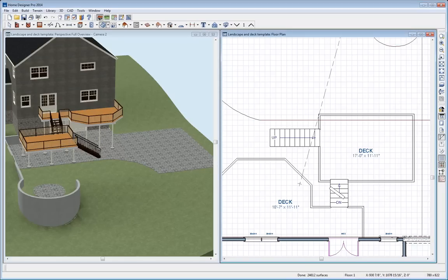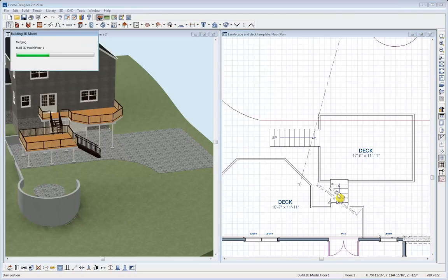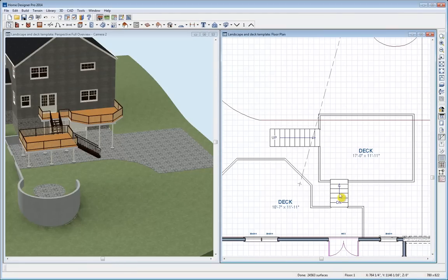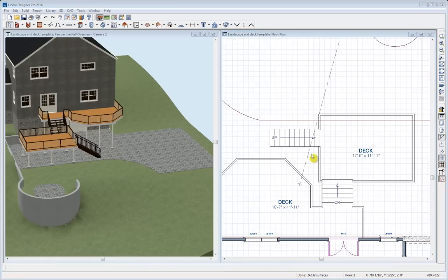And then I do also want to, I accidentally drew out a stair there. We'll select that and delete it. So I wanted to make sure I pressed my space button first so that then I could select my stairs. And we'll pull those out a little bit. I want them to be a little wider. And this one we'll go ahead and just leave the way that it is.